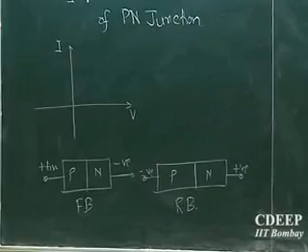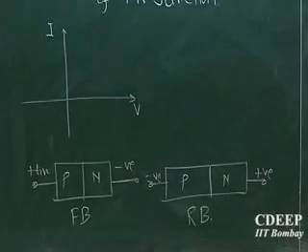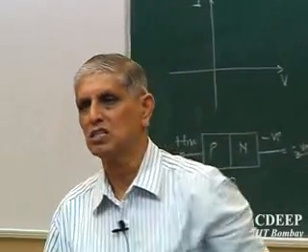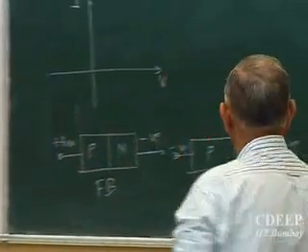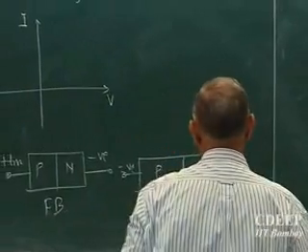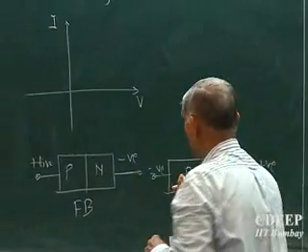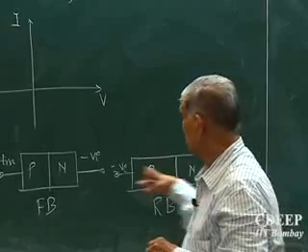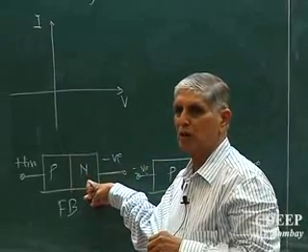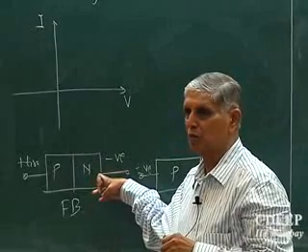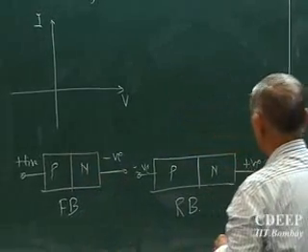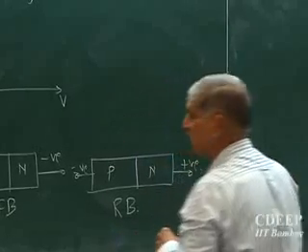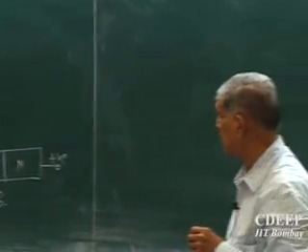And we have seen in reverse bias, the PN junction acts more like a capacitor. That's what we monitored in the CV. However, we did not know how much current in reverse bias was flowing. We didn't know, in case we forward bias the device, how much current it can provide to us. The earlier part, capacitance voltage, was essentially used as varicap or varactors.